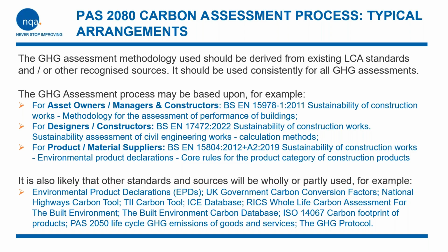the cubic meter of concrete that they supply you, or the ton of steel rebar that they supply you would come with an EPD, which would tell you what the tonnage of carbon dioxide equivalent, the embodied carbon in those materials would be. Life would be very easy if that happened in every circumstance, because the carbon calculations would be nice and easy to do. But if you're a product material supplier, almost certainly somebody at some time has asked you for an EPD or an environmental product declaration. So those are the three main British standards which can help with the greenhouse gas assessment process.